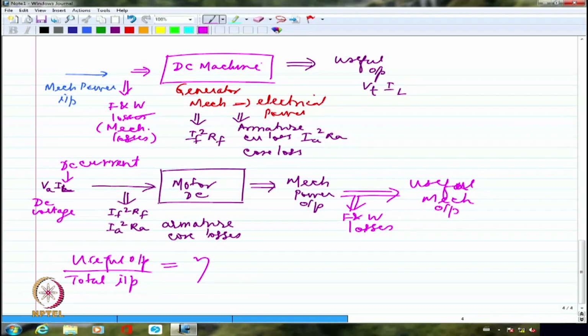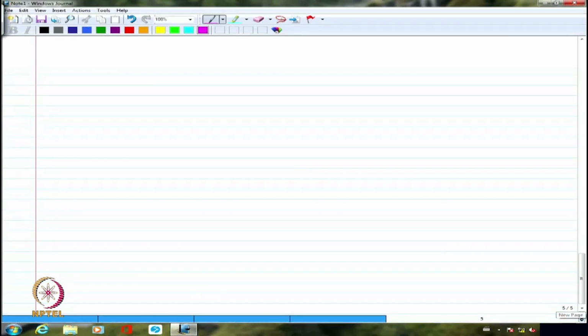So if I am given for a DC machine, it is a 2.2 kilowatt machine, 2.2 kilowatt indicates the useful output that will come out. But when I am giving the voltage and the current, the rated current and rated voltage, if it is a DC motor, that indicates the input, obviously. If it is a generator, that indicates the output. Right? So voltage and current, when I specify very clearly in a motor, is going to indirectly talk about the input.